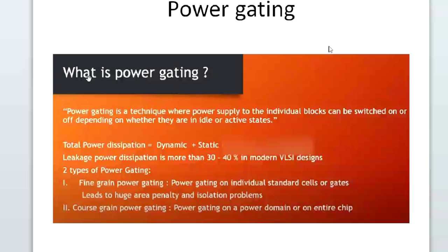So VDD is varied; let's consider two VDDs, one is 1.4 and one is 0.8. Considering 0.8, when we square it we get 0.64, which is 64%. So 64% of the dynamic power is controlled with the help of this. That's why we are considering the multi-VDD option.